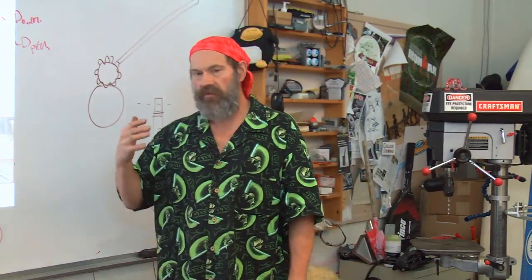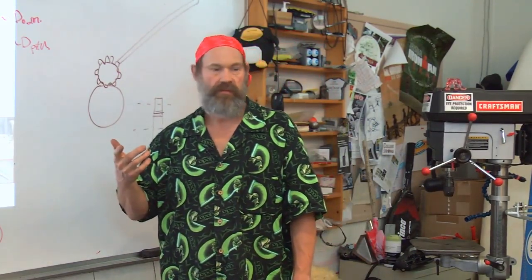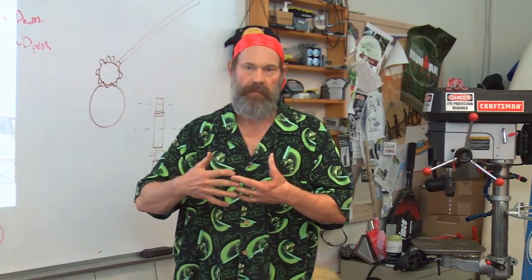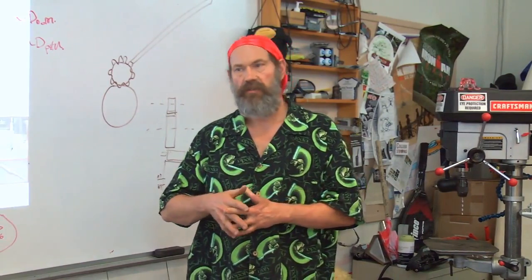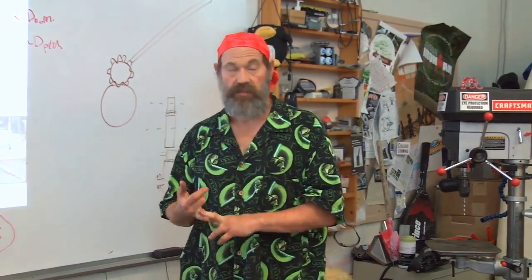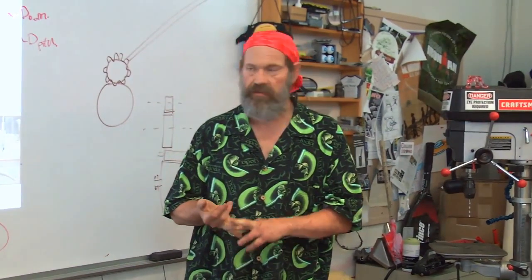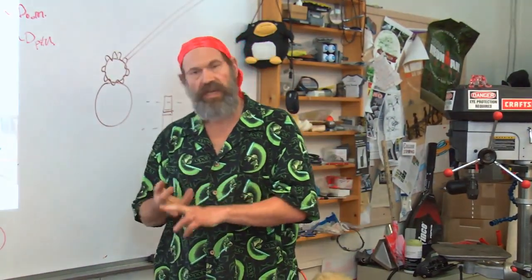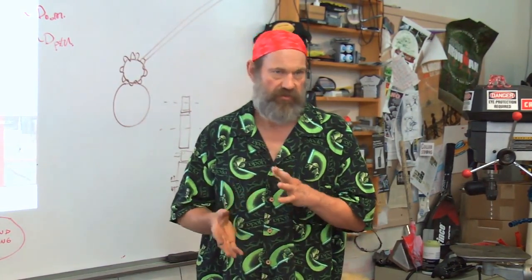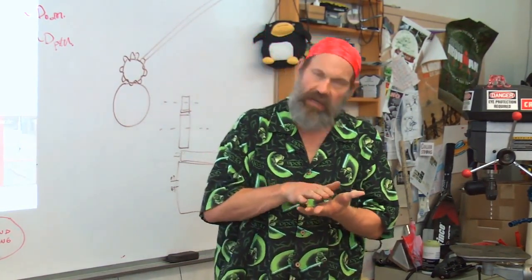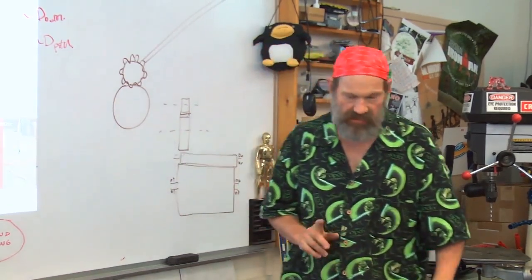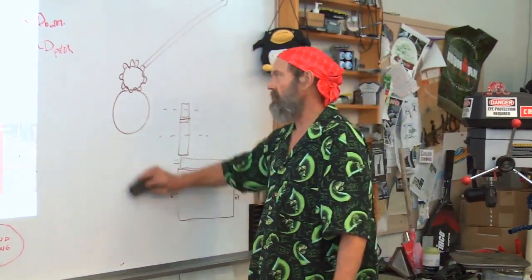How do you do that? Well, if you have the gear design software, you can get the actual exact involute shape you want. That generates the CAD file that you can then take to a laser cutter, or an abrasive water jet cutter, particularly if you're cutting out of aluminum. You can 3D print gears. Beware of how you 3D print them, though, what the strength of the plastic is and the grain of the plastic from the 3D printing process, because that can have a huge effect on the strength of the gears.